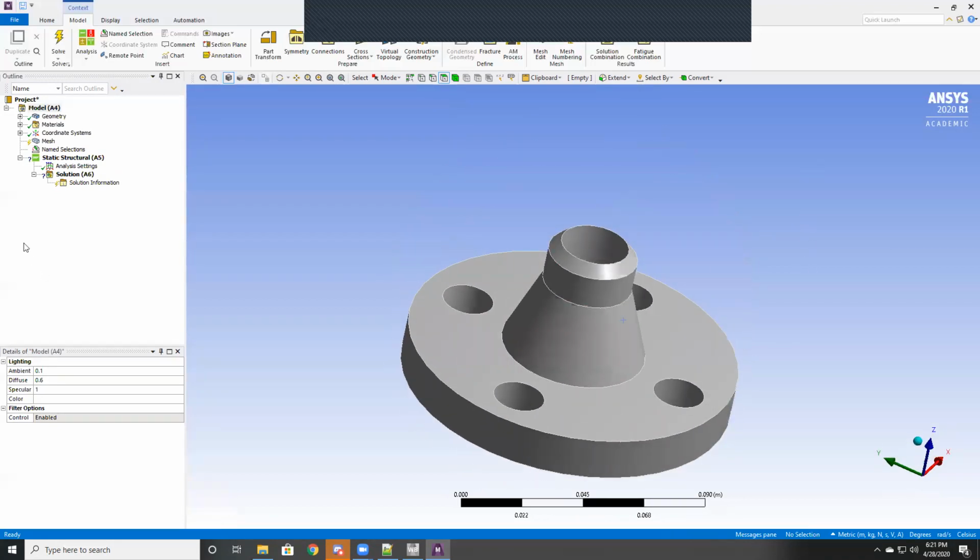So we can assign that, and then when we're later assigning the boundary conditions or the loads, it's really easy to go back and say, I want the outside and I want to apply this pressure there. So that's a really useful thing. It's not necessary in all cases. For a part like this, it's not entirely necessary, but if you've got really complex geometry, it can help a lot.